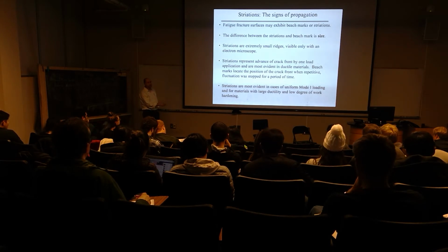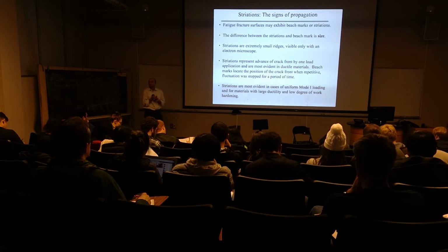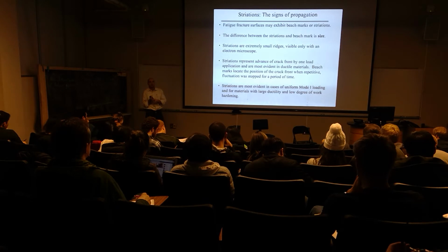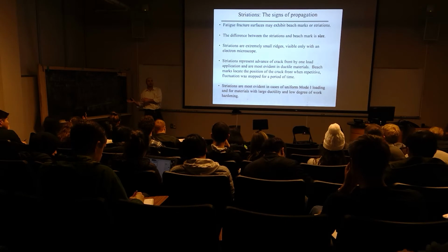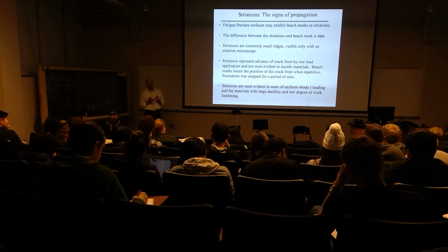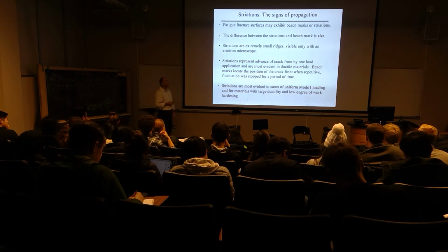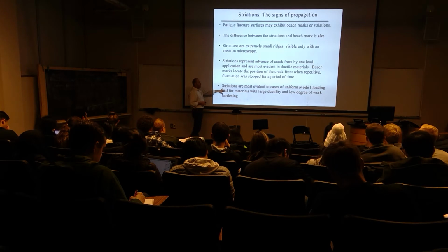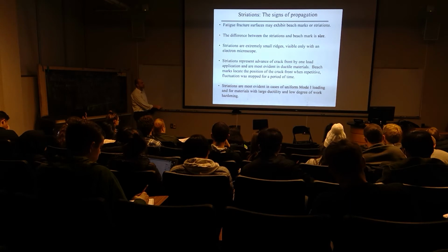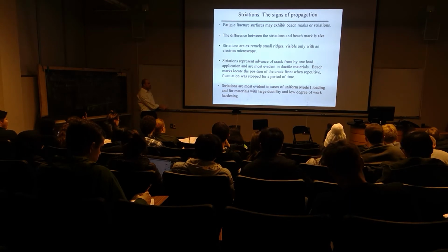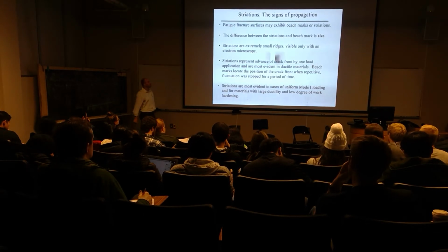And you might see beach marks not being so periodic, because they can be a function of different cyclic environments. So I had my marine, my boat in a particular warm environment, and then I went to a cold environment, and the activity of the corrosion process, the oxidation process in the crack changed in cold and warm. So I would maybe see that on the crack surfaces in that cycle. And then the striations are most evident if that crack was subjected to opening mode load, and this material has large ductility, and that material exhibits very low degrees of work hardening. That means we get the most plastic deformation near the crack tip.